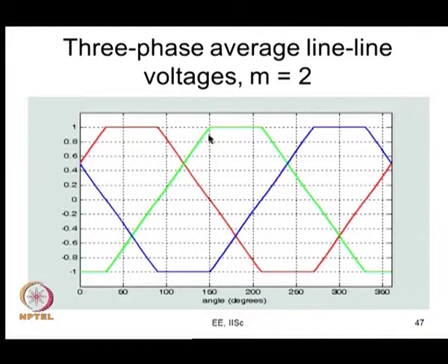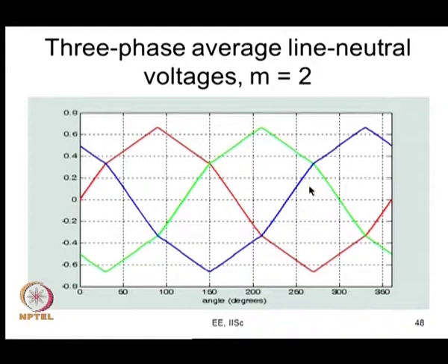And if you take this region for example, what is this? This is VBR. VB the lower device is always on and R phase the top device is always on. And similarly you look at here, VYB is VDC. So Y phase top device is always on and B phase bottom device is always on during this. So you can see that they have started switching lower and lower. So actually for R phase, any particular phase for 120 degree it does not switch, it switches only during those 60 degrees around the 0 crossings, the first 30 degree and the last 30 degree in every half cycle. So you see that there is more distortion.